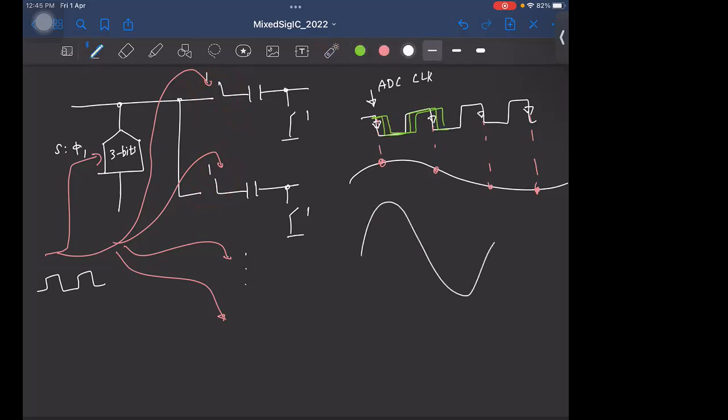That is, if you are designing a very high-speed ADC where you are trying to digitize fast changing inputs, then this is the actual time instant at which you are supposed to sample the input. But say the ADC is sampling here, but it can so happen that this switch here might sample the input at this point, right? And another branch can sample here and so on. So this will again introduce errors, right? So we are having a lot of errors here. So based on the discussions we have had in many classes, can you suggest some technique to correct for this?